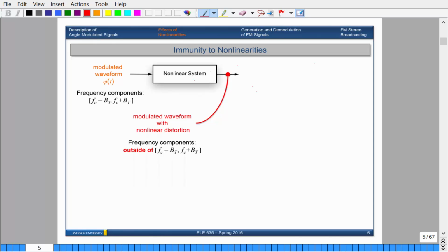As you start applying nonlinear operations, the width of your frequency components will become larger and larger, depending on how much of a squaring or how much of a power term you apply to each of the components. Because you are increasing the bandwidth of the signal, you could put a bandpass filter centered around the carrier frequency, and make sure that the width of the signal is whatever is deemed by the transmission bandwidth.